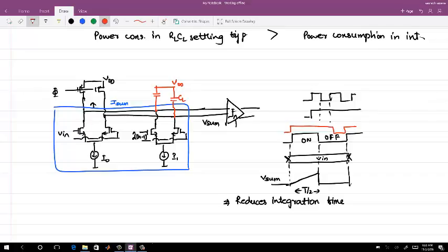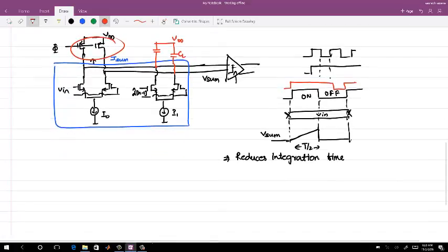And the other reason is, if I want to reset in 10 picoseconds, the same node which I was resetting in, let's say, 25 picoseconds, I have to increase the size of this PMOS now, because this has to charge the node up to VDD. And if I increase the size of that, you will see the increased parasitic capacitance come into the picture. So the capacitance will hit it. Okay. So on the mean, you are still seeing a gain of 1.5 times. That is still a gain, but this gain is no longer 3.